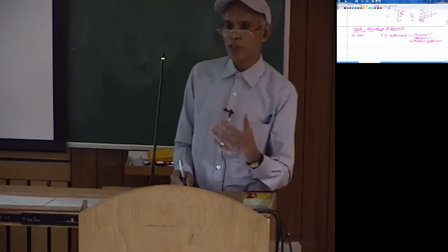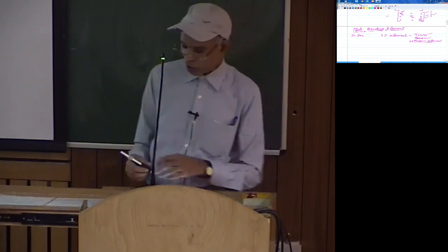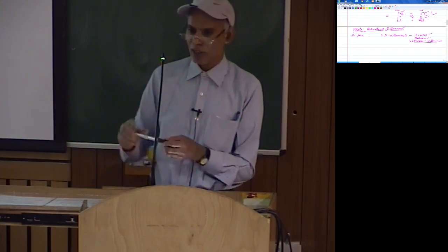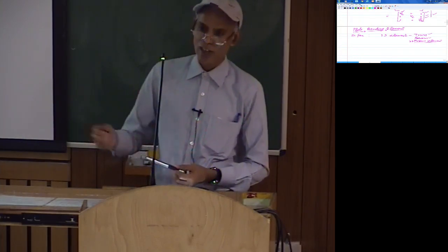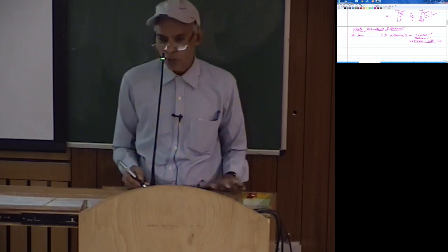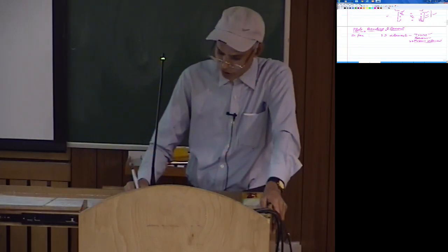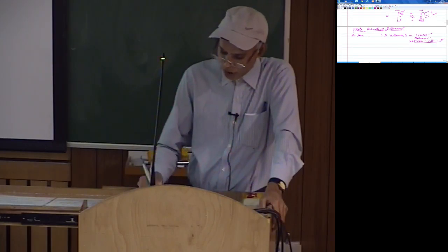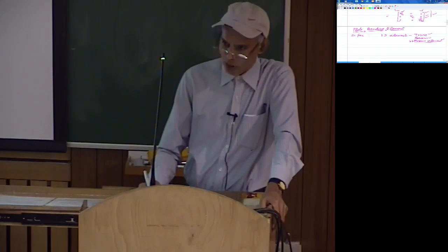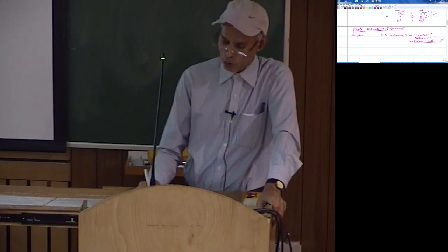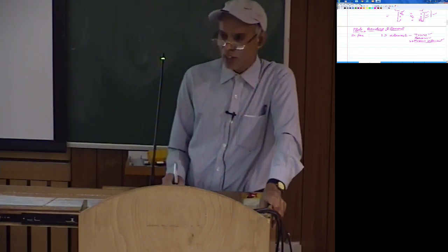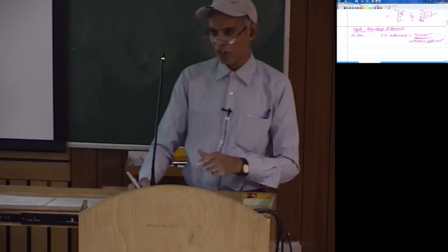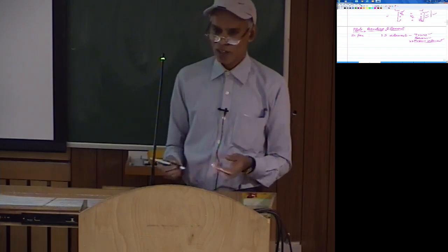And for now the frame can be 3D as well. Then you need to consider bending in two planes, one plane and another plane, and maybe you can include twisting and axial deformation. That of course I did not cover, but it's a straightforward extension. One can also talk of a 3D frame element similar to 2D, like in the truss we discussed 2D transformation and 3D transformation. In a similar way you can have a 3D frame element, but then you have to augment the bending in two planes and the torsion, twisting of the beam, and also of course the axial.